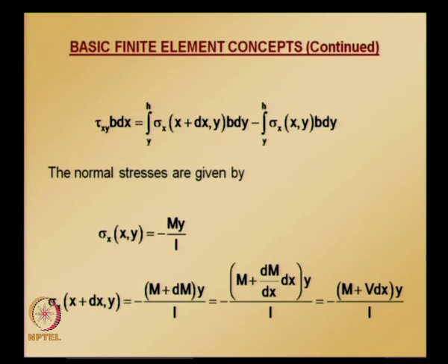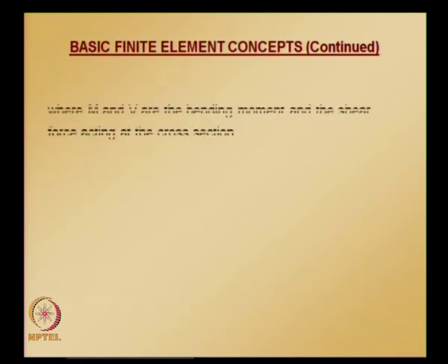Now we can substitute these into the equilibrium equation we have written by considering forces acting at a distance y from the neutral axis, and here capital M and capital V are the bending moment and shear force acting at the cross section.